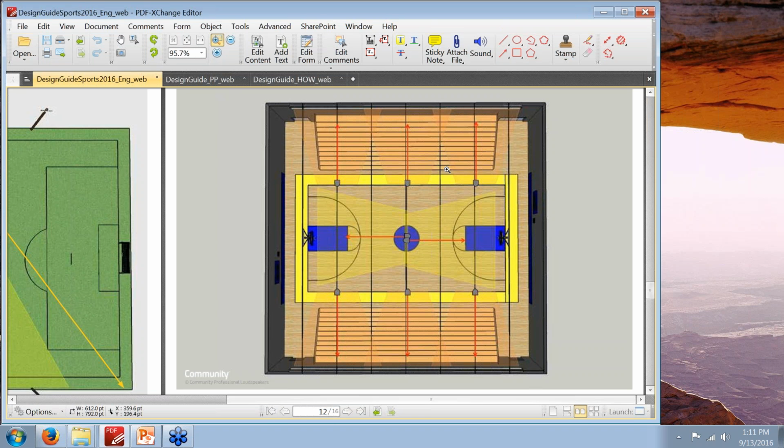We find in general that rooms like this that are very reflective benefit from the directionality or the tight coverage pattern that comes with an R-series product. They're also very durable. They're built to withstand outdoor conditions. So indoors they do pretty well dealing with stray basketballs and things like that. Putting them close to the audience here along the sidelines keeps them out of the way of whatever game is being played on the court and shortens up the projection distance, and that helps keep intelligibility higher.